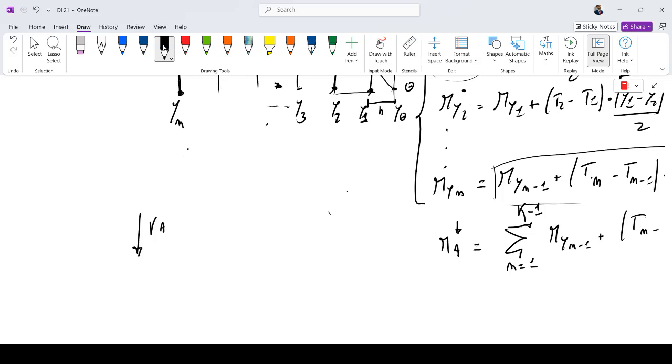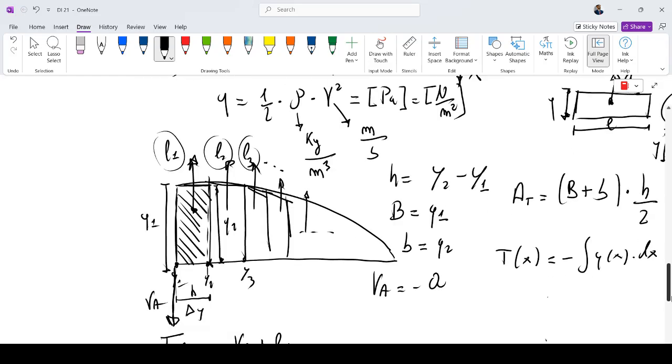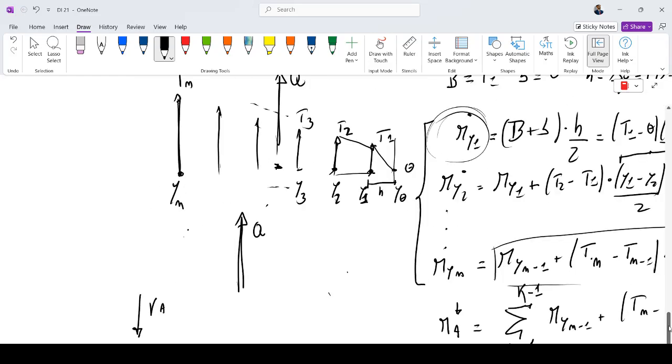This is VA. We must know where the Q lumped is applied, that is the summation, if you remember, of all the local loads, but the distribution is not uniform, it is quasi elliptical. So this X is generally 0.43 to 0.46 of the half span.